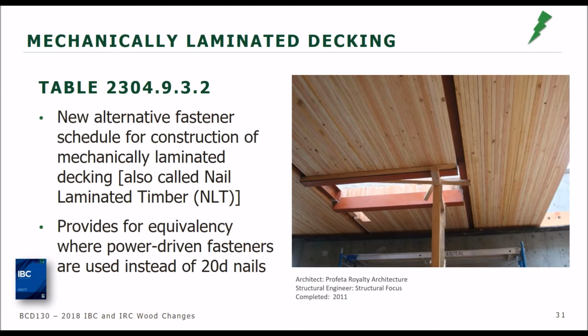So we've included some tables that'll provide those equivalencies to the 20 penny nail that had been pretty much the standard since, as Michelle noted, those provisions were included in the UBC, they were included in the NBC. I'm from Wisconsin. The Wisconsin Commercial Building Code had nail laminating provisions like this, the 20 penny nail provision, since about 1956, if my memory is correct.